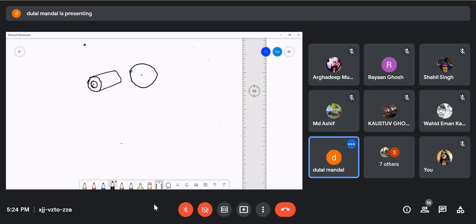Center means you put it in the vice horizontally and turn it. If you turn both sides, you will get a square on this, that you have seen in the videos. Now draw the diagonal, and you will get the center.